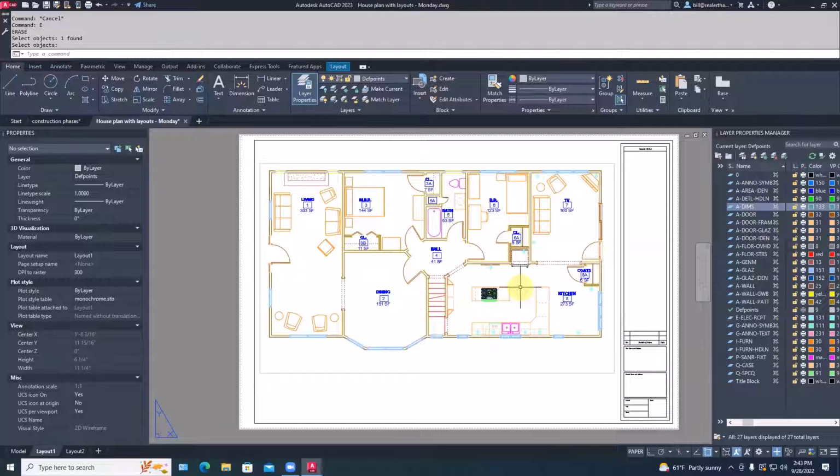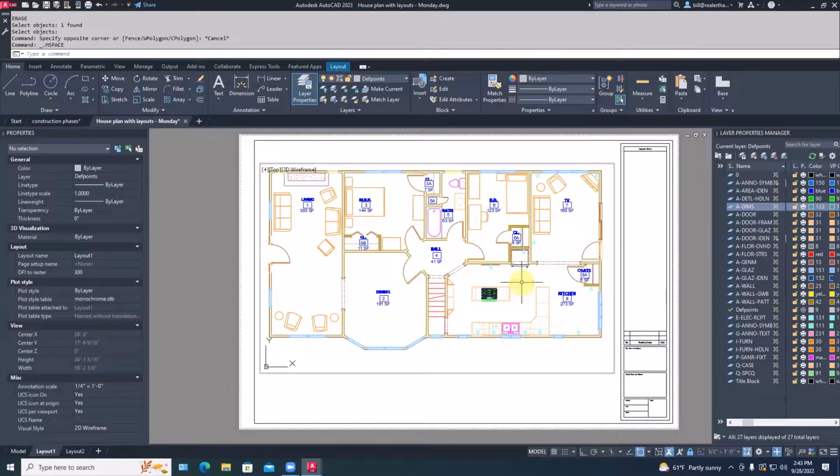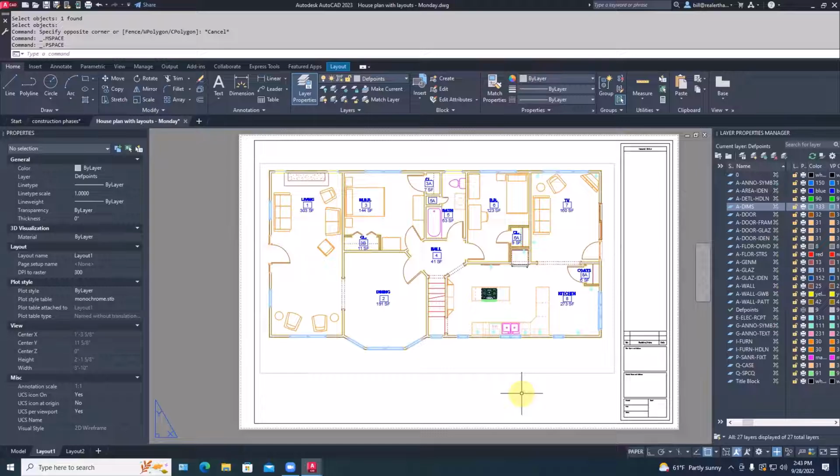Okay, if I were making it in model space, that would mean I would have to double click in there to make this active. But we're creating these dimensions out here on the sheet, not inside the view. They're sort of drilling down to find those points, but the actual dimension is out here in annotation space, if you like. So we want to double click. We don't want this to be active.